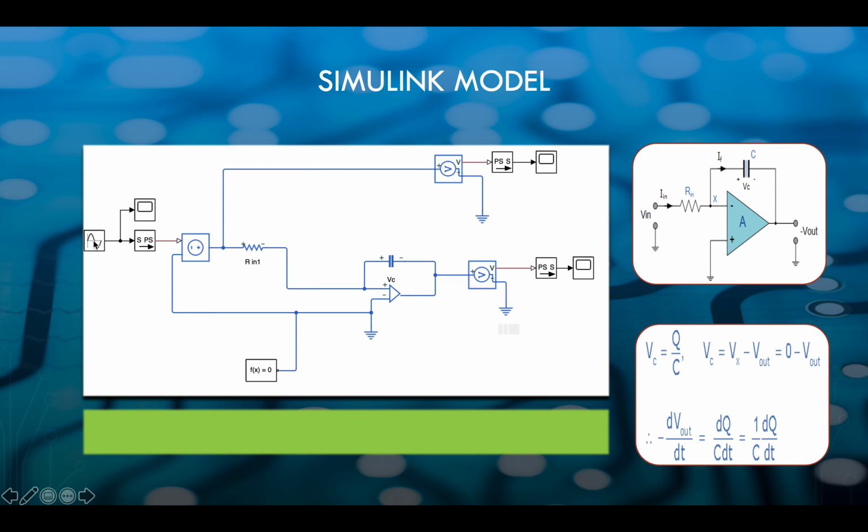This is basically a sine function that you would have in Simulink, but to use it in here, you have to put it through an algorithm that gives it some physical modeling properties. Once you do that, it behaves just like a regular physical circuit. Then you have to transfer that signal back to a Simulink signal, something that it can read.